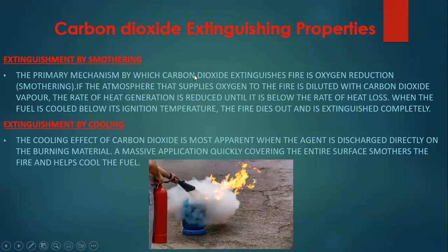Moving on, carbon dioxide we have discussed. The white cloudy appearance is because the liquefied carbon dioxide has converted to a solid form. It removes oxygen, and this white cloudy appearance can absorb heat, but only to some extent. If the object is still heated up, reignition can occur. That is why carbon dioxide has very limited use on class A fires.